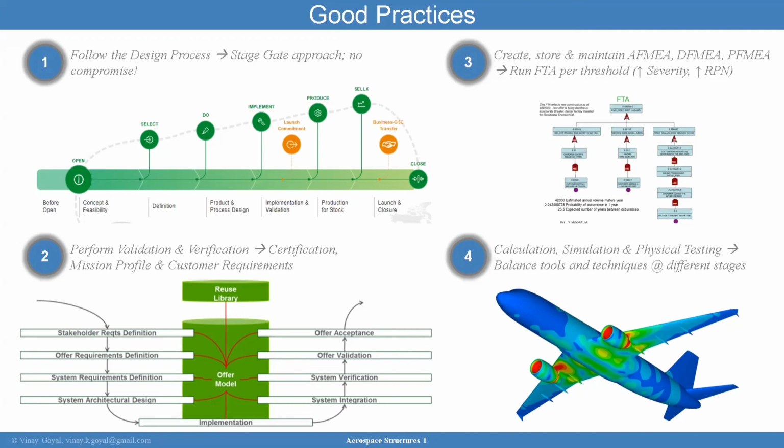Just imagine if the engineers back then would have had a simulation tool that could have told them that on those squared windows, you will have stress concentration on the corners, and it is the effect of the pressure differential. They would have noted that. They would have made the design change, made those corners rounded, and avoided a lot of things. Sometimes we need to really accept reality, and I think Professor Goyal was also saying this. You have to accept reality, and when we do not understand the underlying physics, unfortunately, that understanding will come when you have a catastrophic failure.